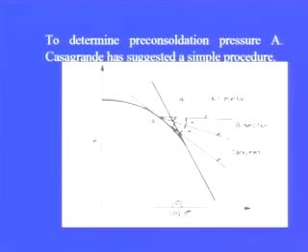For that, a method is given by A. Casagrande to determine whether the soil will behave as normally consolidated clay or as pre-consolidated clay. From the same e versus log sigma bar curve, we can obtain the pre-consolidation pressure, or over consolidation pressure, and then decide whether the soil will behave for that particular stress range as normally consolidated or pre-consolidated clay. The method is very simple.